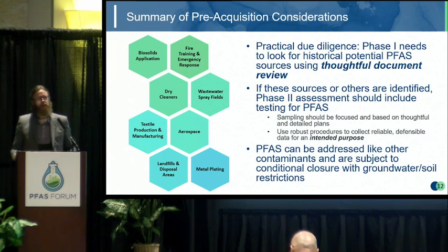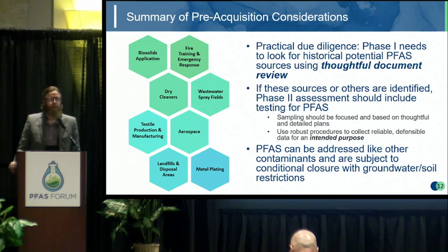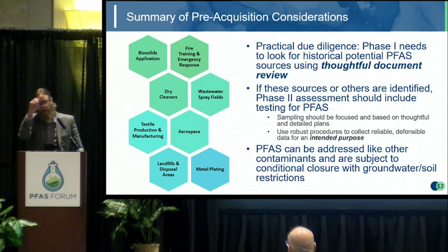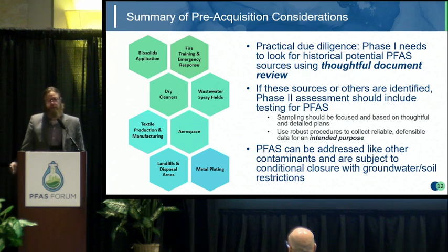I really think our main issue around PFAS, the risk that we identify the most for our clients, is just the possibility of very large offsite plumes, because PFAS is such a mobile constituent. That's one of the risks that we're afraid of. We have one site a client was looking at, and they have wells, and they have one well right on the border of the property. The groundwater flows right off the edge of the property, and that well has a really hot PFAS hit.